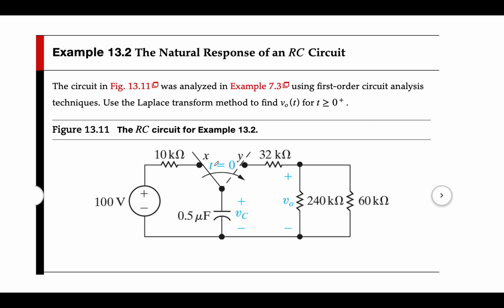As you recall, basically capacitors become open circuits. And so between these two terminals, our V sub C, which is going to be the initial condition on the capacitor, for t less than 0, that capacitor looks like an open circuit. So all of the 100 volts is going to appear across the capacitor. Just to have the picture in front of you while we talk about this.